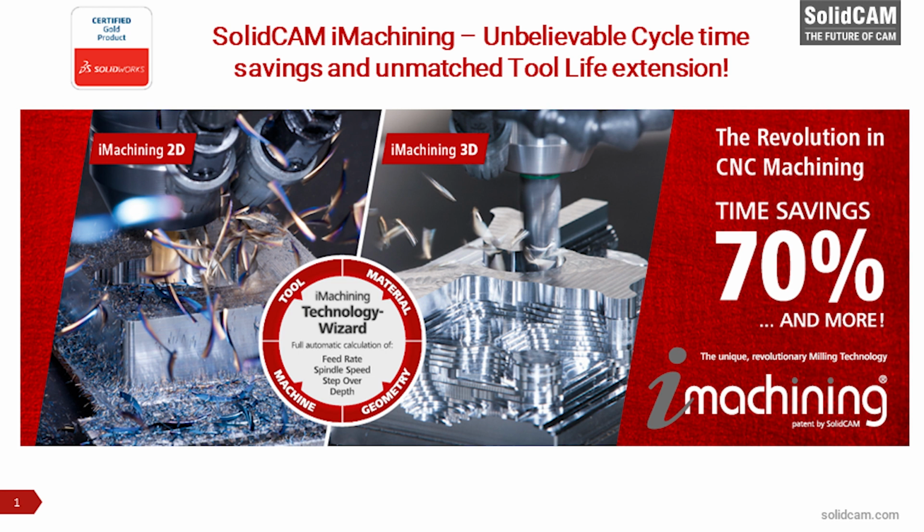The default settings, if you just go like I showed earlier where I was using the auto settings and you use the actual out-of-the-box condition of iMachining, it's only going to run between 17 and about 22% spindle load is what it's designed to target. Now, if you go in and you make adjustments to those data structures and you start dialing them up and increasing them, you can really put it where you want to put it.